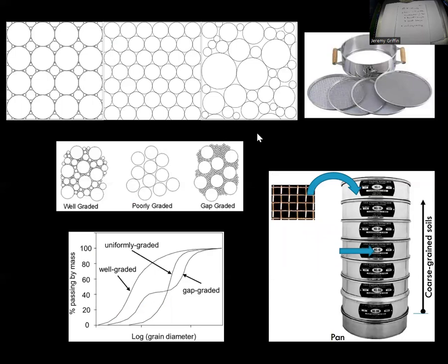Next couple of days, when you guys come in tomorrow, I'm going to have you build a sieve. A sieve you can use to separate out a soil sample and see what mix of sand grain sizes you have. Because if you have what's called a well-graded soil sample, where you have large, medium, and small grains of rock sizes, that will actually create the strongest concrete.